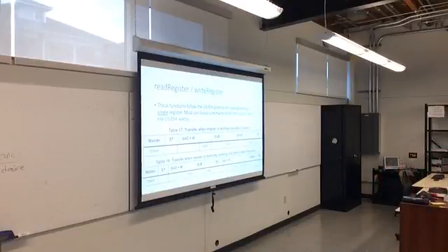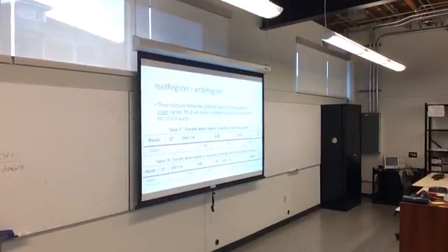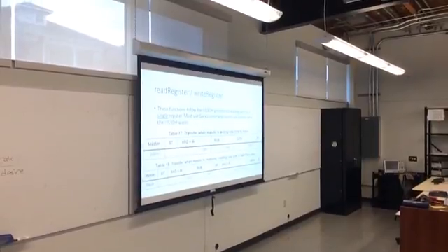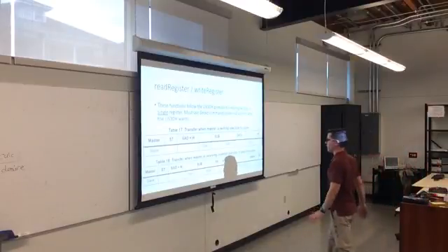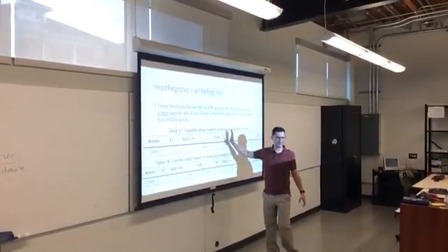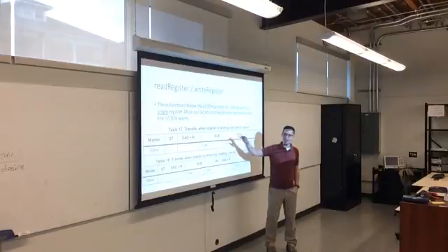So it passes in an address, and data, or returns data, whether or not it's needed. There, inside of the accelerometer data sheet, there are 2 timing diagrams, if you wish to call them that, that say how to do writes and how to do reads. They have them both for single bit and single byte and multi-byte operation. We're only going to do the single byte reads and writes.